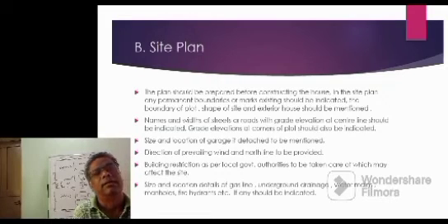Size and location details of gas line, underground drainage, water mains, manholes, fire hydrants, all have to be mentioned. Otherwise, at the time of excavation, it may clash with our construction work. So all this has to be indicated in the plot plan.